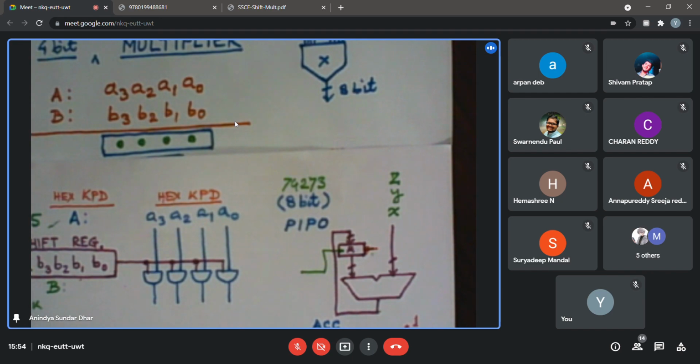Particularly to capture the spurious states, if anything is happening between 2 clock edges, then you may need to step using ticks, so that it is not advancing by 1 full cycle at once. But otherwise, if you are running it for say 60 cycles, then you need to click 600 times if you use ticks. So choose it appropriately. Maybe you can set it to cycles first to see what is happening in every clock cycle. Otherwise, you need to click it 10 times.